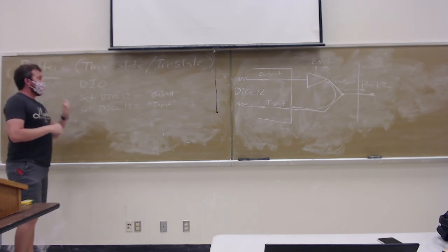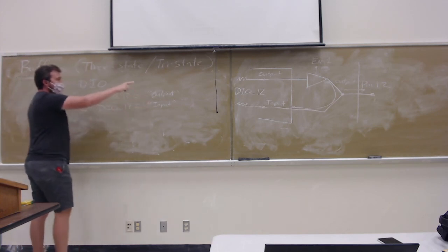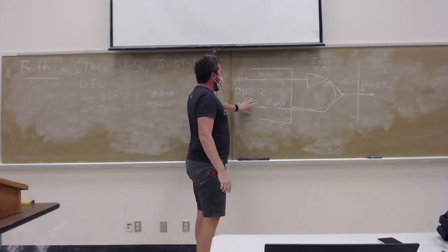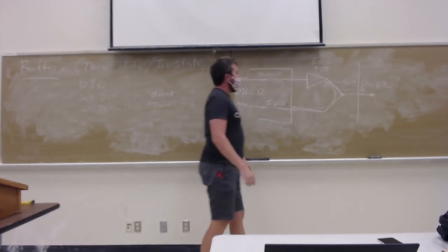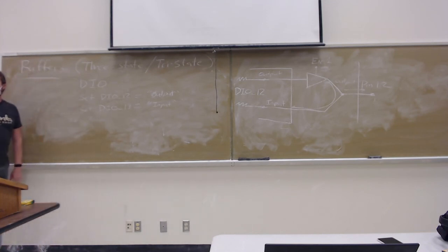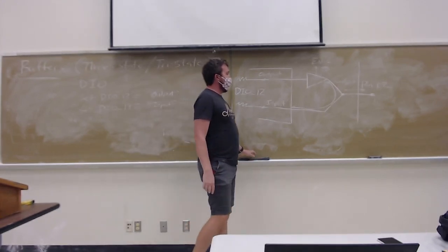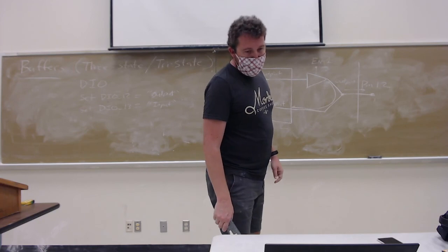So that's what happens under the hood. When you set digital input and output pins on your microcontrollers, such as an Arduino, to outputs and inputs, you're taking advantage of the fact that every one of the pins has an output port and an input port, and that output port is attached to a tri-state buffer. Any questions about that? The answer to almost any digital design problem is almost always, let's just put some tri-states on it. It's like turning it off and on again.